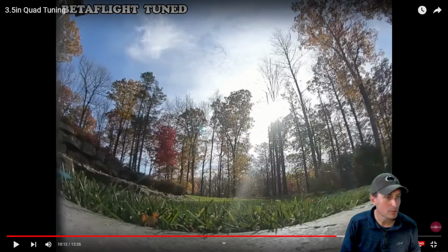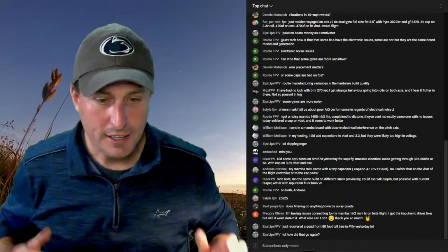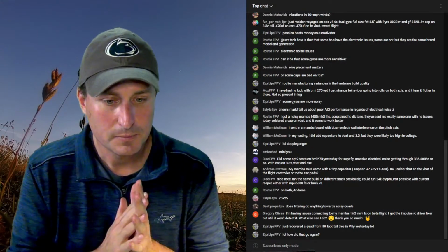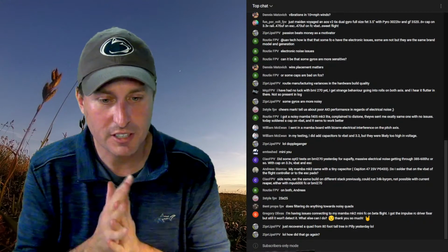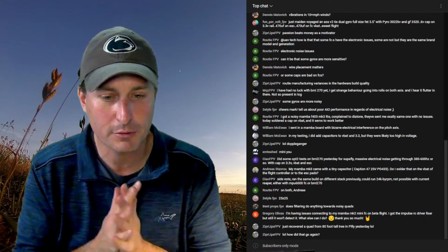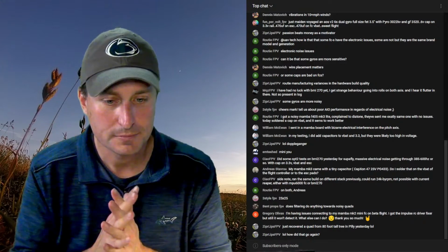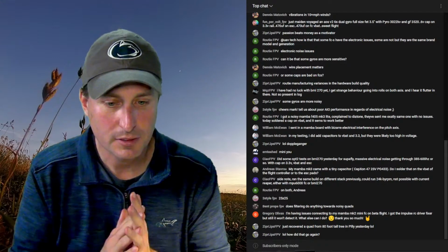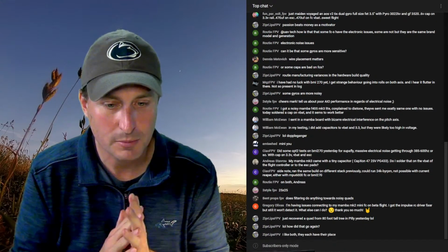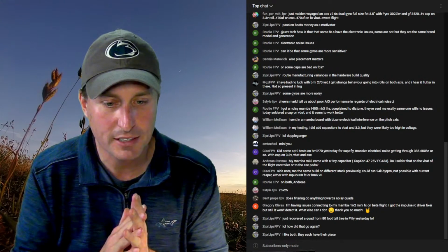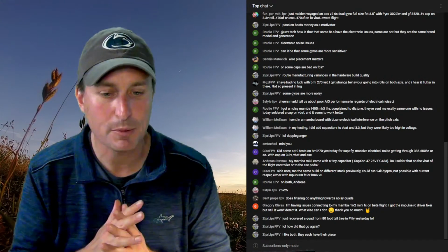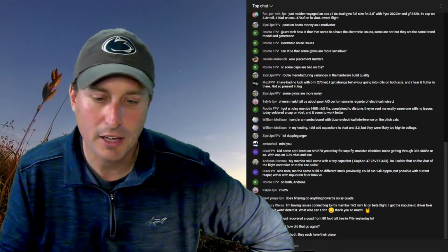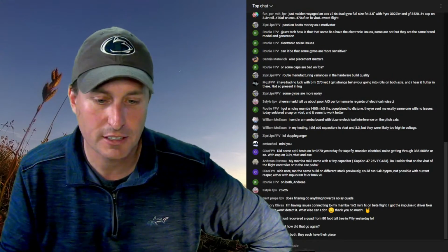All right. So with all that, let's get into some questions and answers here. Rowdy FPV says he had a Mamba 405 MK3 Lite, compliments of Diatone. They sent him an extra, same noise issue today. He soldered a cap on VBAT and it seemed to work better. Yeah, so a cap on VBAT is the first place I would go, because you probably have some extra around. See if you can get it on there and see if it helps.